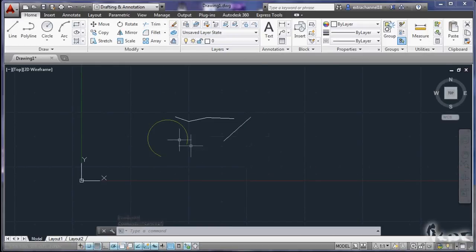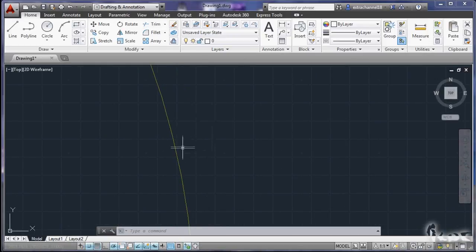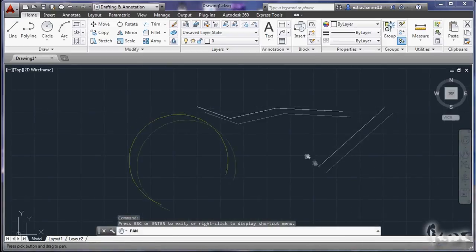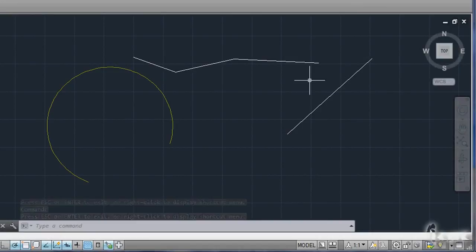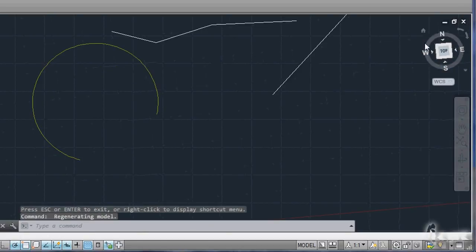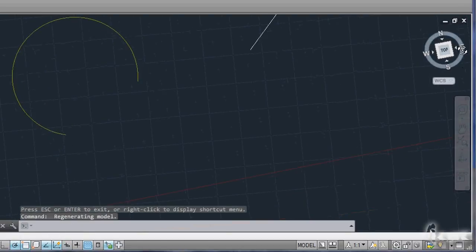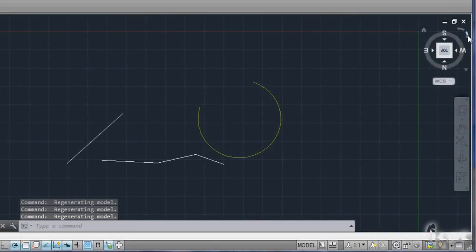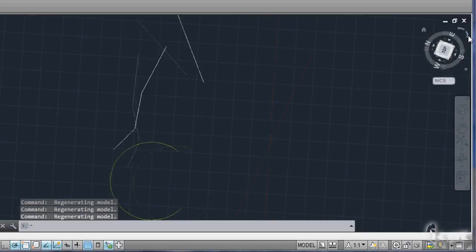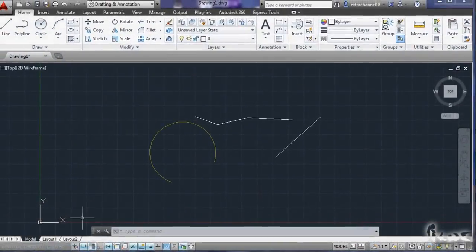Zoom is set simply through your mouse wheel. Use the pen button on the right to move through your workspace to check it better. To check your project, you can use the 3D map on the right. Until you go with 3D projects, the cube will show only the top face, meaning that you are watching the project up to down. Click and drag the circle with cardinal directions to rotate your whole workspace. You can use also the hidden arrows in the top right corner. This does not rotate objects, but just your point of view or camera.